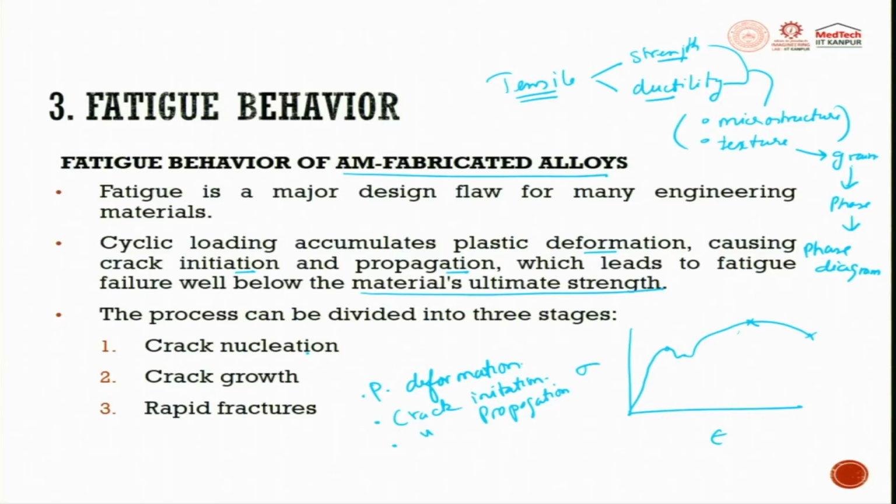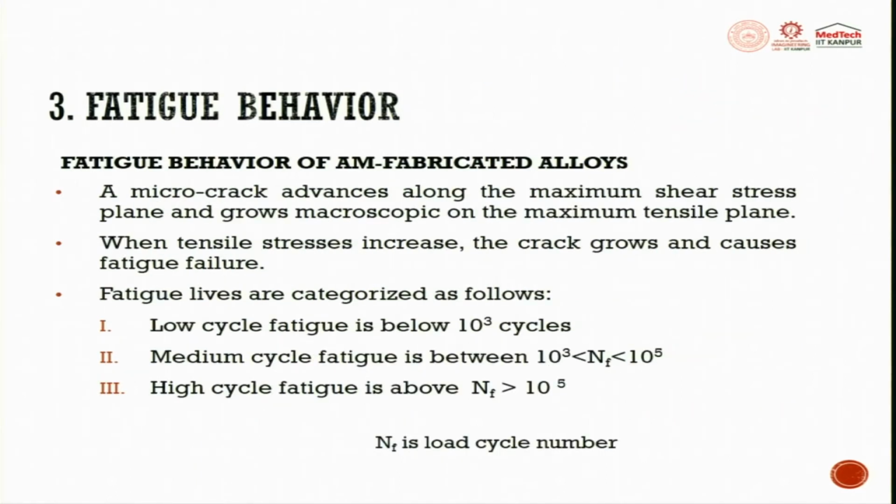Moment you initiate a crack, then depending upon the cyclic load, the crack can grow very fast. Moment it starts growing, then it is going to have a rapid fracture and you will have it into two pieces. So, these are the very important steps which are involved in fatigue behavior of any given sample. A micro crack advances along the maximum shear stress plane. This is very important.